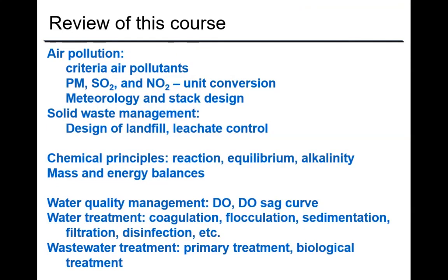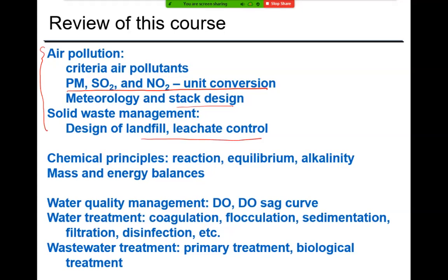So finally, maybe we can use 1 minute to review this course. Okay, so this is the introduction of environmental engineering. As you can see, for each section, it's really just glancing through the topics. So for the last section of this course, we talk about the air pollutants, right? The criteria air pollutants, there are 6 of them. We talk about the PM, sulfur dioxide, nitrogen dioxide, talk about these unit conversion, meteorology, and stack design. So for the solid waste management, we discussed the design of the landfill and the leachate control.